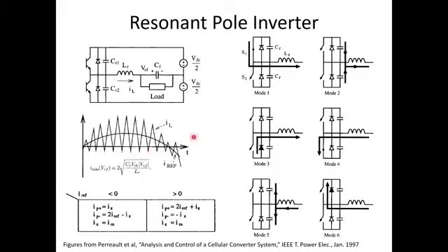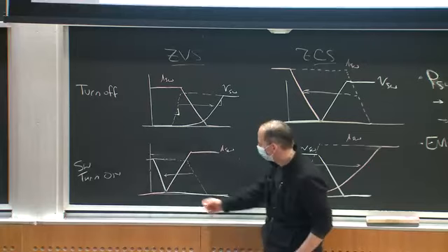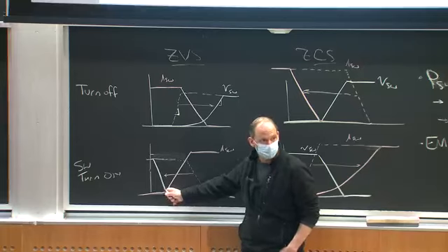What I'm going to do is let this negative current build up to a minimum particular value, and I'll call that IP minus, for example. And eventually, I can turn off this bottom switch, and the pre-charge current in this inductor is going to resonate with these two capacitors again. I turn off the bottom switch with 0 voltage switching because of the capacitors. This inductor will ring with these two capacitors until the top diode turns on. And once the top diode turns on, I'm getting 0 voltage turn on the top device again.